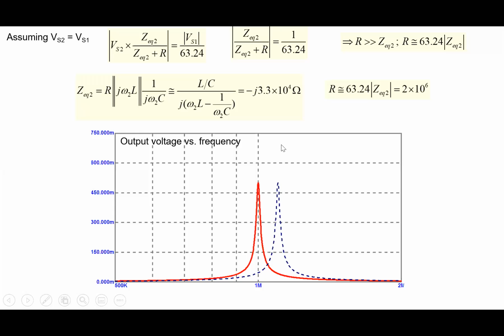That is what is happening in radios and TVs. Some L and some C is being changed in order to select a particular radio channel or a television channel. These are calculations which tell you how you can do those things.